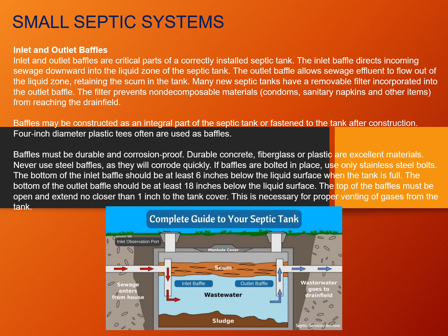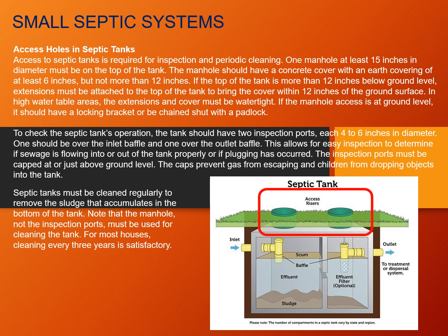When designing septic tanks, make sure you have an inlet baffle and obviously an outlet baffle wherein the treated sewage water is going to the drain field or to the city sewer line. There should be access holes for the septic tank. Please read through the text to determine what size is required. But for the inspection of the septic tanks or for cleaning of sludge, for most houses, cleaning every 3 years is satisfactory.